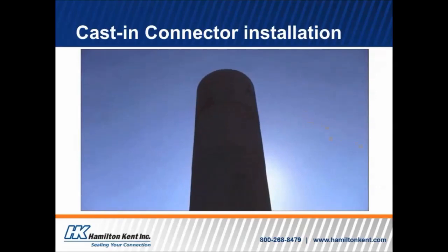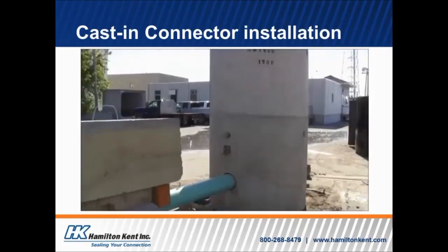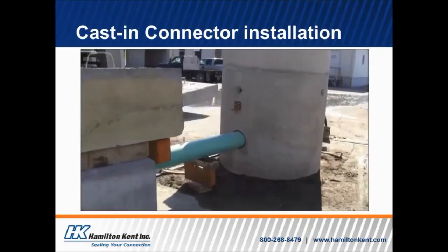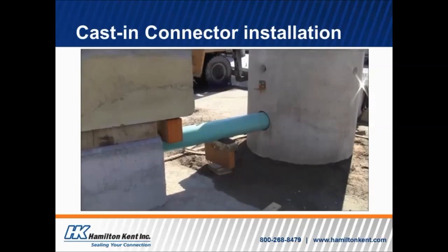And then they decided to do some testing, and this is something that we encourage. You don't have to set it up exactly like this, but this is how they did it. They stacked several manhole risers on top of a base, and then they put the pipe in through the mandrel, and then they can apply 13 psi of water pressure just by filling up that stack of manholes.